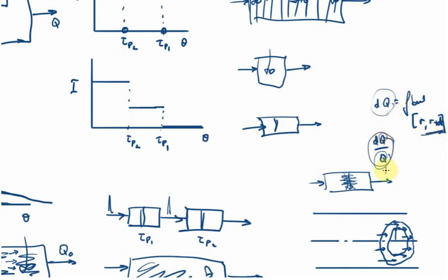So this is the fraction of the fluid in that radial position, and because we know radial position equates to space-time, it's also the fraction of the fluid in that age. So there's a particular age that applies to fluid at these radial positions. So this is the fraction of the fluid of those ages.